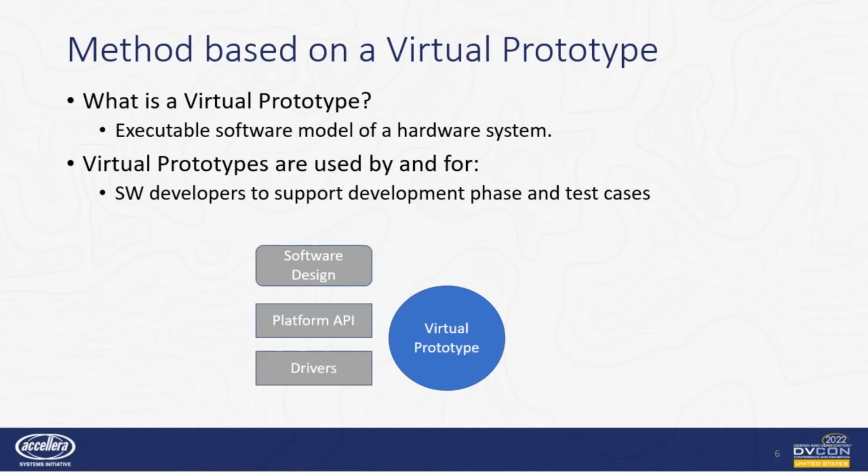Change of the core in a microcontroller unit not only represents a hardware change, it also involves significant changes in the software domain. Software toolchain adoptions are needed, as shown previously. Applications have to be ported to the new MCU. Functionality of the application for the new microcontroller unit has to be validated.